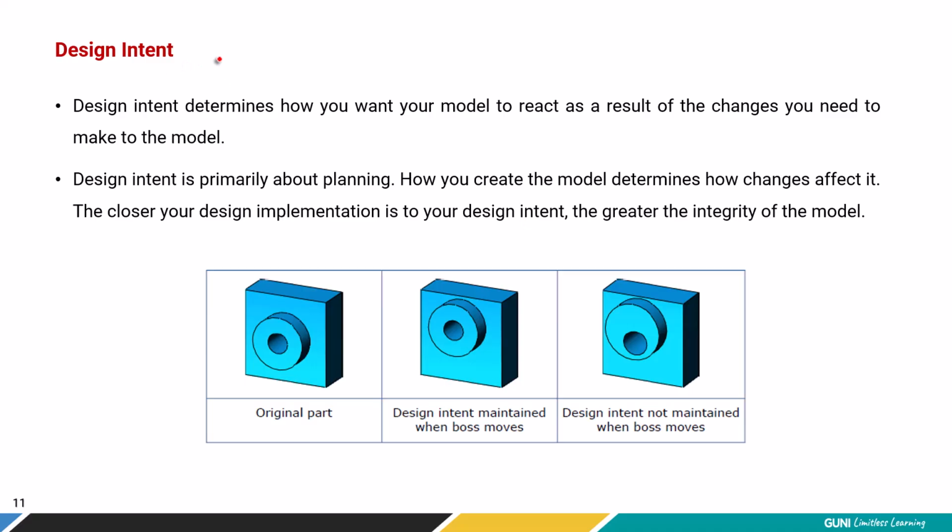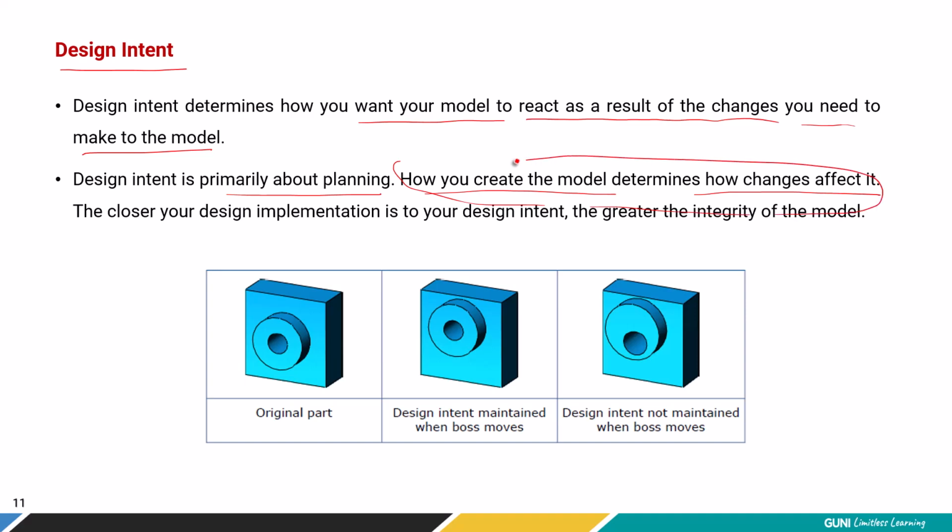Now before you design any part in SolidWorks, you must know the concept of design intent. Intent means intentions. Design intent determines how you want your model to react as a result of changes you need to make to the model. So design intent is primarily about planning. I'll discuss what exactly it means. How you create the model determines how the changes affect it. This is very important, and this is what makes the design intent. The closer your design implementation is to your design intent, the greater the integrity of the model.